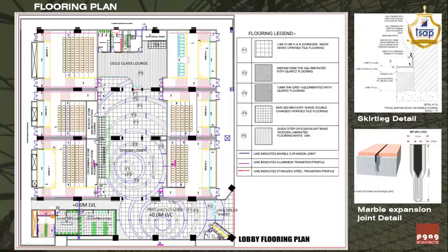In this slide, I'm particularly showing you the skirting detail also. Now, sometimes, as explained to you, the lobby slab level is down by 300 mm. So we need to consider the filling, and as per the site condition, he will calculate the filling so that the final lobby finish level gets matched with the outside passage and the entry passage level.